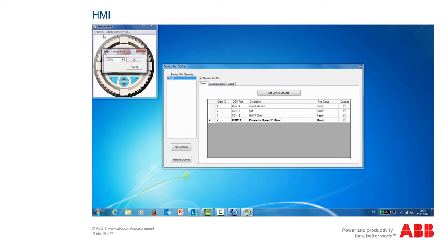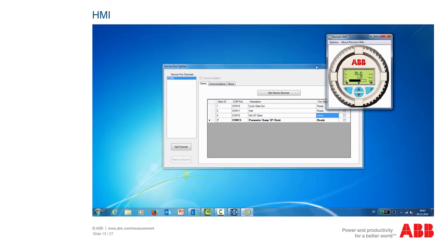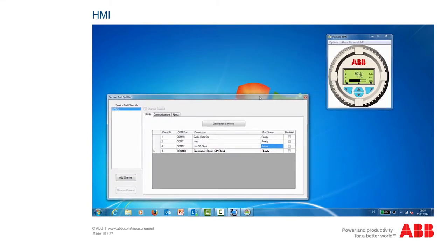To enter the service code, click the right-hand button on the virtual control unit once to call up the menu. Then, using the down arrow button, go to the service item and confirm again with the right-hand button. You can now enter the service code and confirm again with the right-hand button. All service functions are now released.